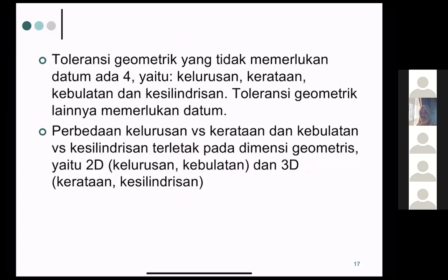Okay, I think this is for additional notes in Indonesian for all the classes, so I'll just put it here so you can all read it. So we have 4 geometric tolerances that don't need a datum: kelurusan, straightness, kerataan, flatness, kebulatan, circularity, and then kesilindrisan or cylindricity. Okay, the other geometric tolerances need a datum.